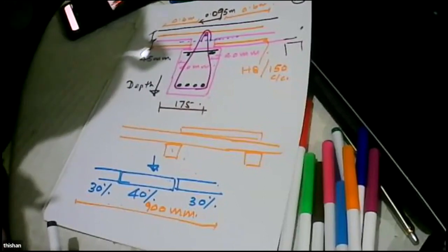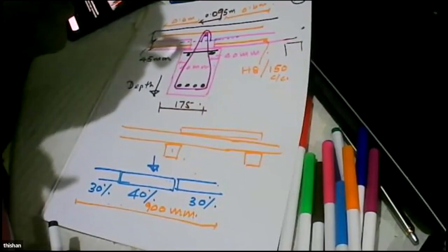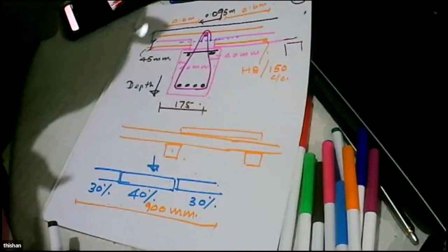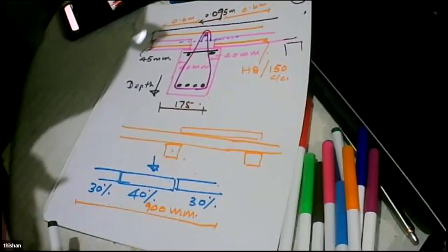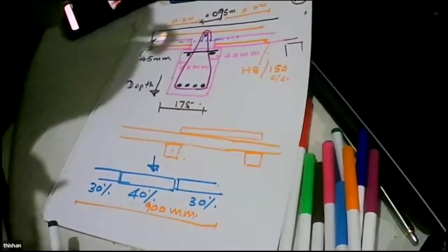One more question: is the imposed load enough, since the above slab load is acting during the casting? No, during casting we have props. Mathematically the whole system is on props as long as we are casting. So without a big error, we can reasonably assume that everything is cast monolithically and design the reinforcement accordingly. Is that clear? Yeah, that is clear, sir.